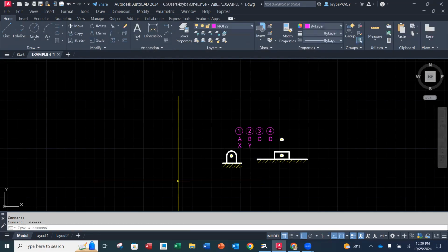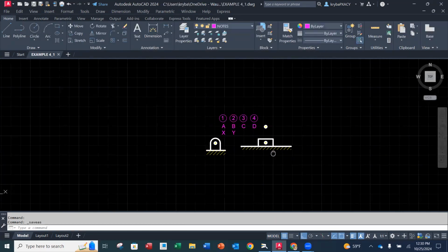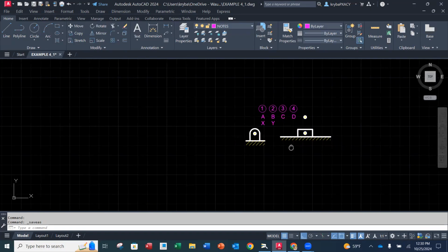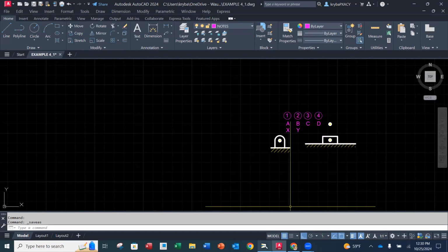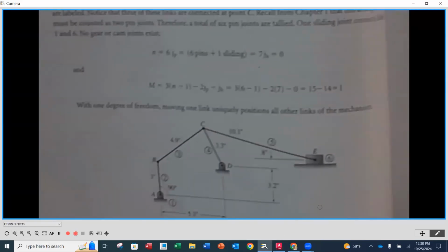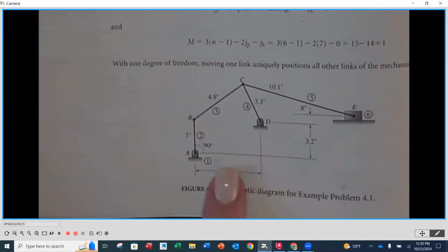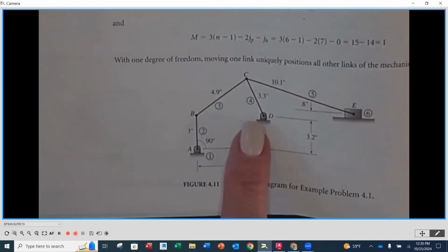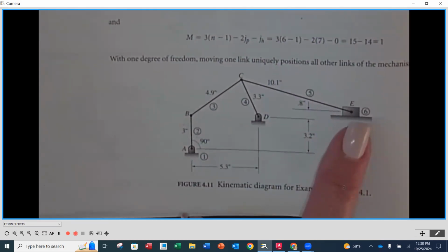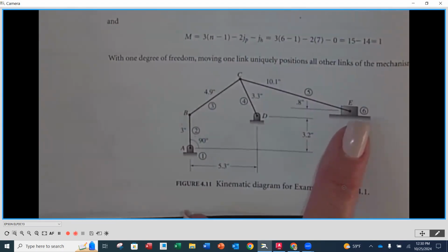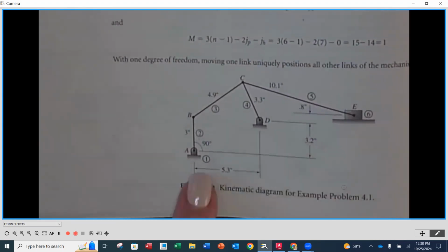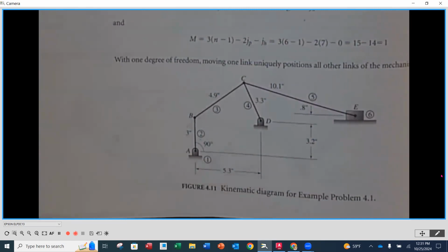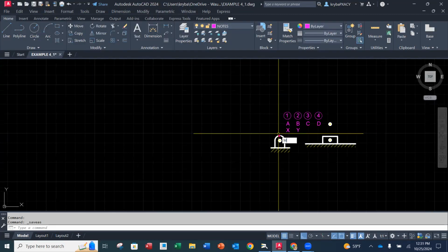There we go. Okay. All right. And now what we're going to do is just make that kinematic diagram. So I am going to use, at the bottom of page 76, the home position right here. I'm going to need 2 frame members and 1 slider. Okay. So I'm going to start here at my A, go back over here, and I'm going to move.